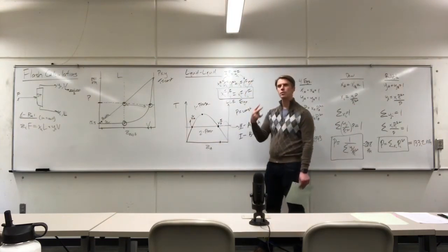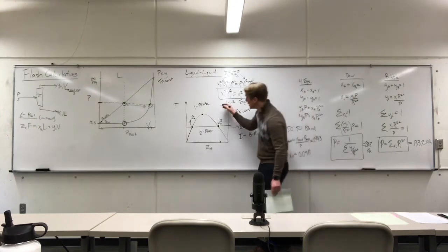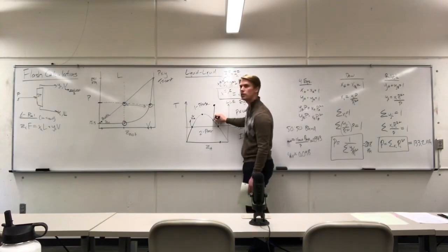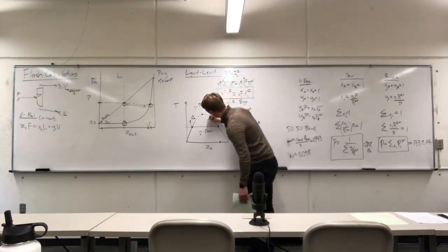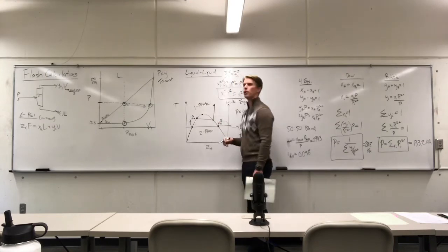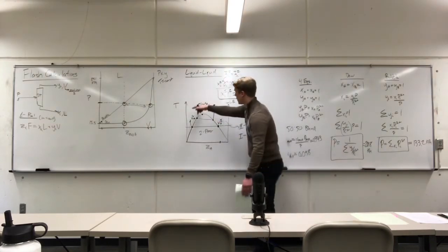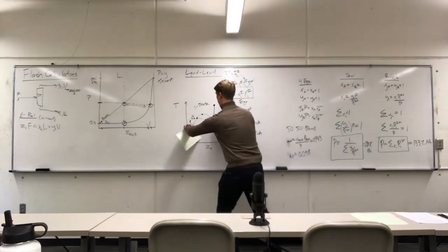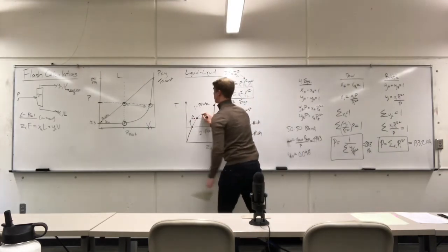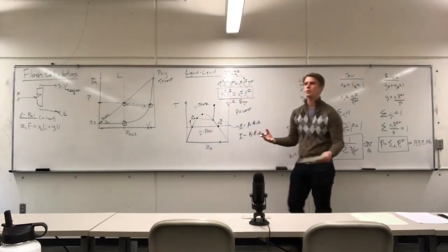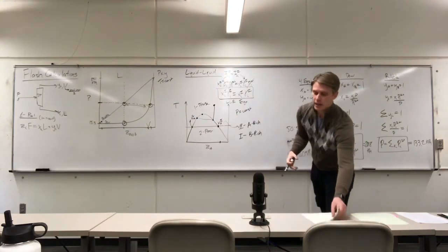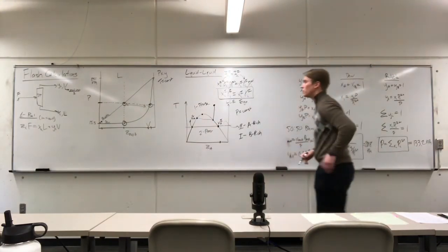So instead, I do these flash calculations where if I had a system in a single phase region, I dropped it down until I hit a phase transition, then I can use my governing equations to lock in that point right there. And then I do that at a bunch of different conditions, and I can effectively draw a series of two points until I get to what would be called the upper consolute temperature, where the two fluids are in equilibrium. Now with polymers and liquid-liquid systems, you can get all sorts of really funky behavior.